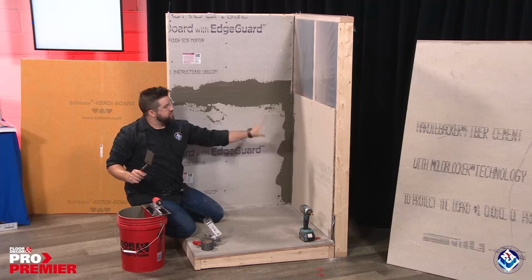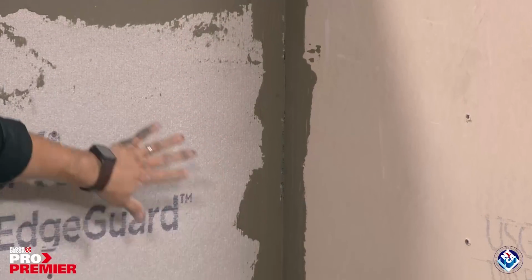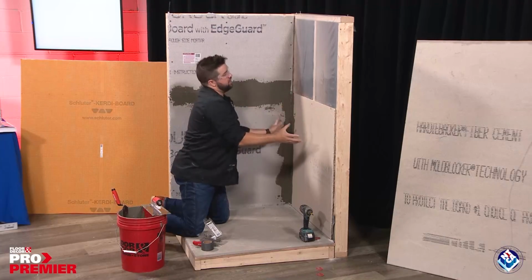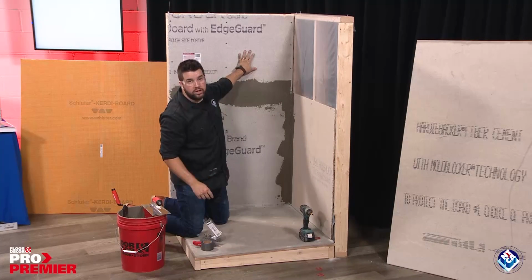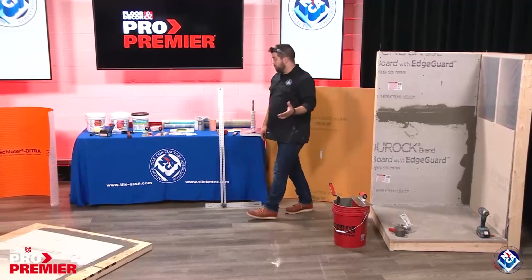Now if we were going to continue installing fiber rock on this wall, we would do the exact same thing as we did over here. I would place a couple of screws as spacers, and then I would put my next board on top of that, leaving that gap. Exact same way I did this wall over here. So let's move on to talking about membranes.